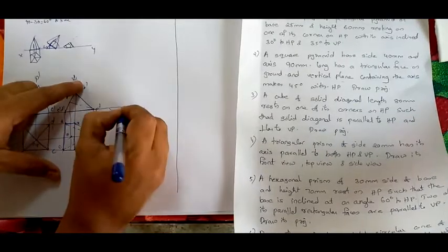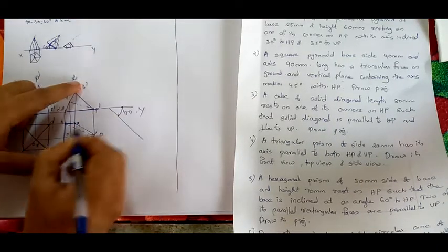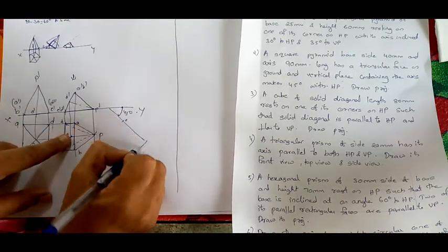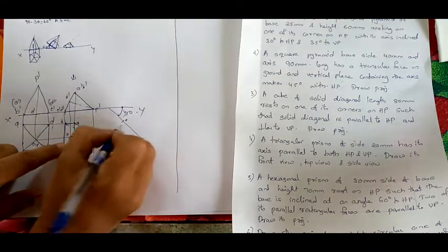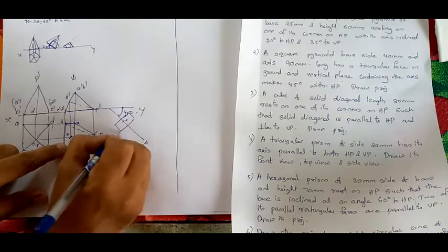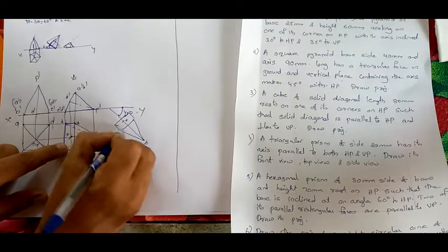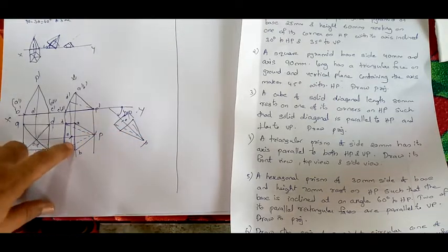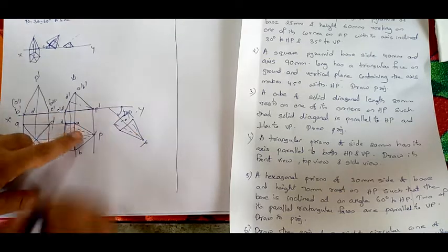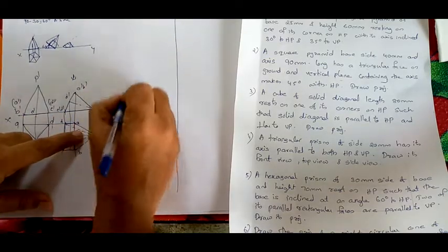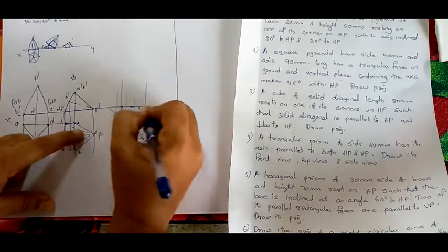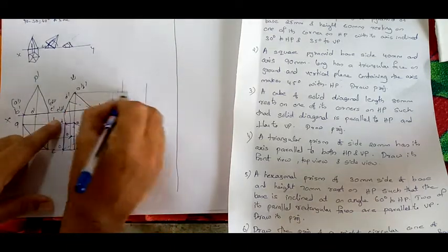So take 45 degrees, draw a line, and on it mark OP. The axis is making OP, so mark it. Now redraw this figure here. I will not be redrawing it, you already know how to redraw this figure. Redraw it in such a way that axis OP is making 45 degrees. Now from here project upwards and obtain the corresponding view. It's easy, right?